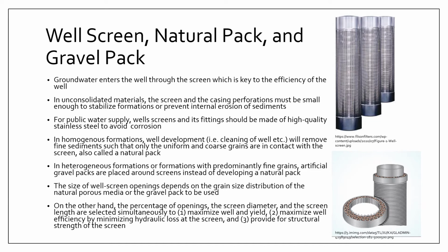And another consideration in your well screen is the size of the openings. And typically the size of the openings should be small enough to prevent internal erosion. All right, and that sizing will be based on the grain size distribution of your aquifer. And we will discuss that later on, how we determine the well screen size openings.